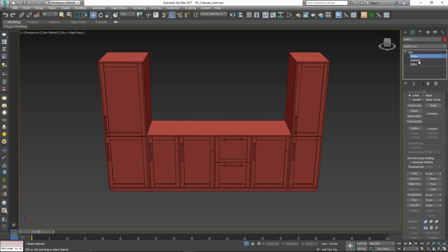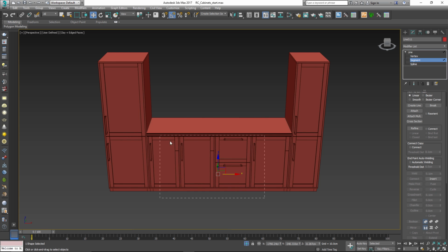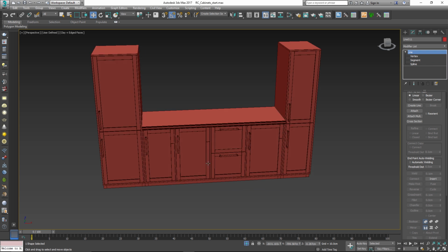And of course, sometimes you may not even want a worktop on top of the cupboards, especially for larders or if you're using the style for wall cupboards. In this case, you can turn off the worktop by selecting the spline segments, then right-clicking and changing the type to curve. And that just about covers the parts of the style that can be modified using the spline itself,